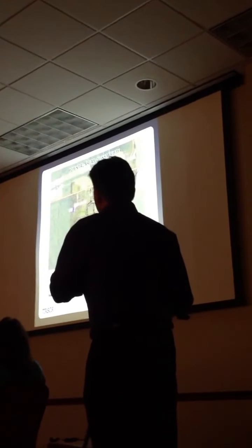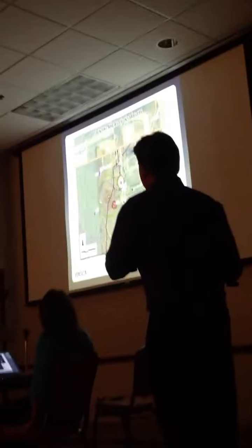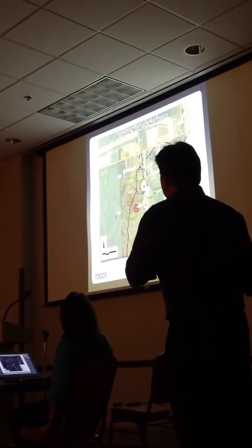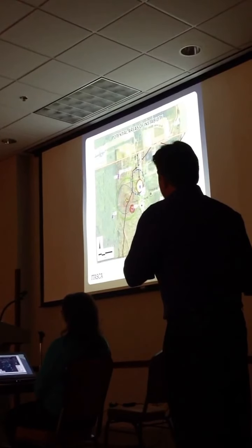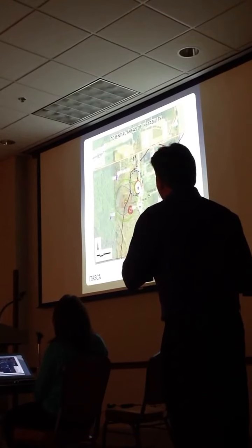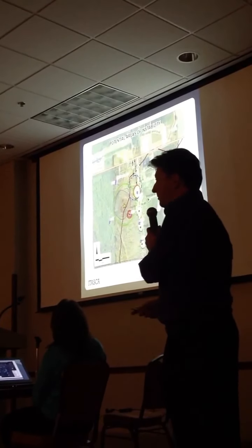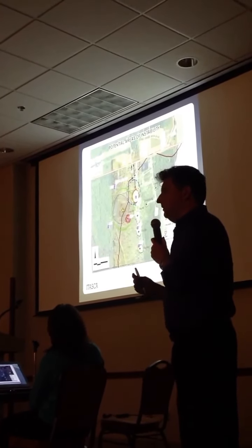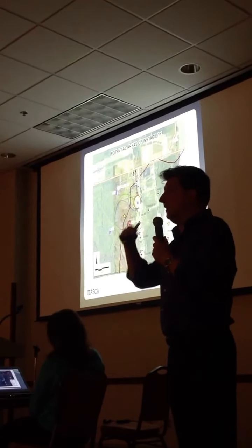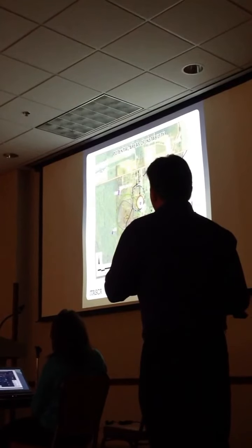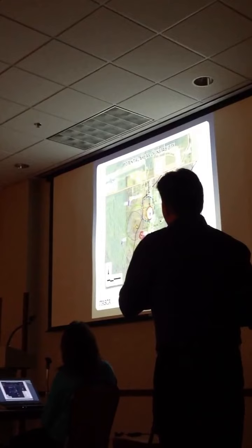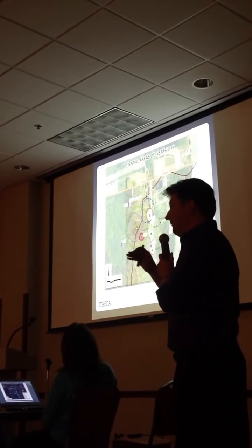So this is this disturbed rock zone that we are talking about with Oxy 3, that we've been able to model very effectively, and this is the sinkhole that's there, on top of this disturbed rock zone. In the case of Oxy 1, the most likely thing that would happen, if it were to, is that the roof would come in. And in that case, the sinkhole would be formed immediately above the Oxy 1 cavern, most likely.